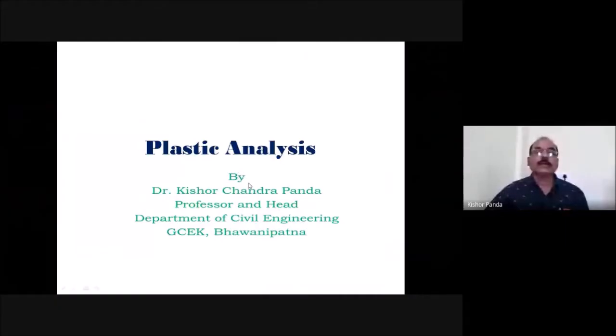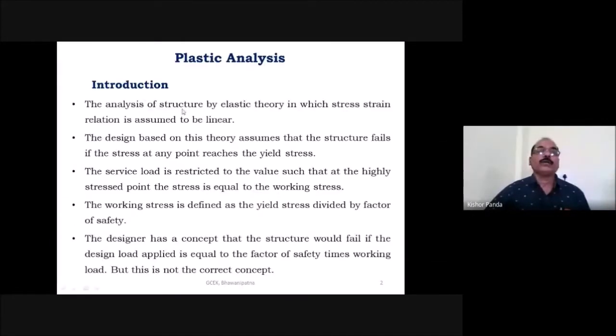Today we will start the last module, that is plastic analysis. First you have to know what is elastic analysis and plastic analysis, what is elastic theory and plastic theory. So you know already what is elastic theory. The analysis of structure by elastic theory in which stress-strain relation is assumed to be linear.